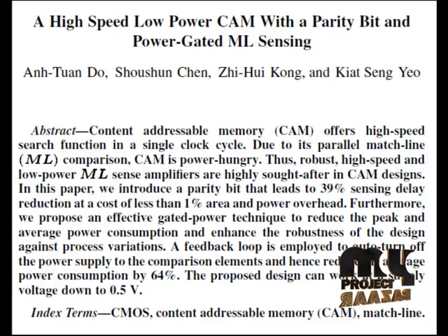For example, consider a CAM consisting of 4 words, with each word containing 3 bits arranged horizontally. There is a match line corresponding to each word, feeding into a match line sensing amplifier, and there is a differential search line pair corresponding to each bit of the search word. A CAM searching operation begins with loading the search data word into the search data register, followed by pre-charging all match lines high, putting them all temporarily in the match state.